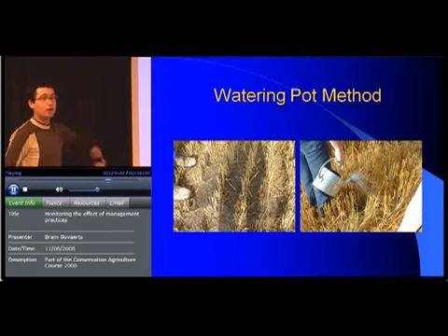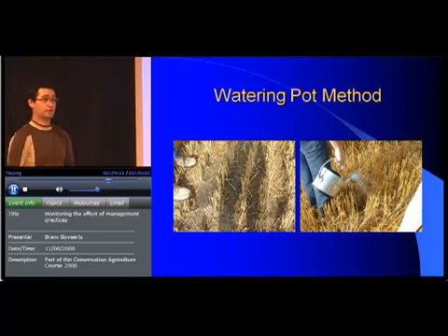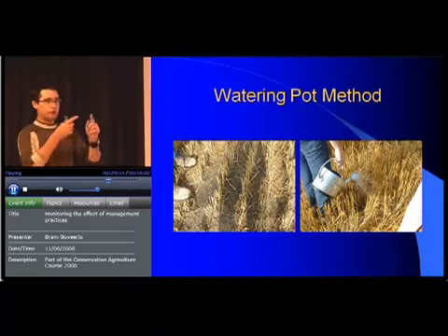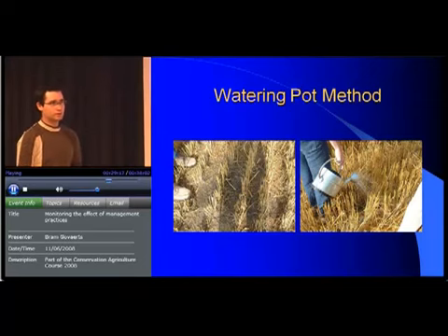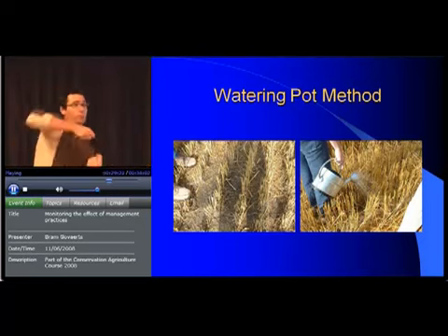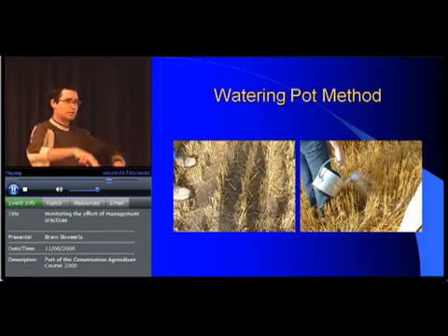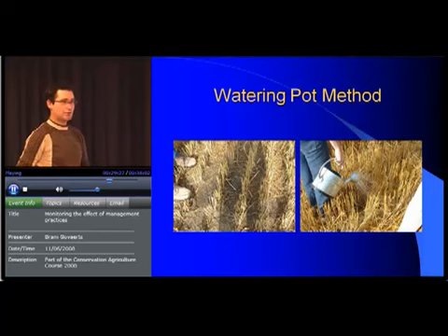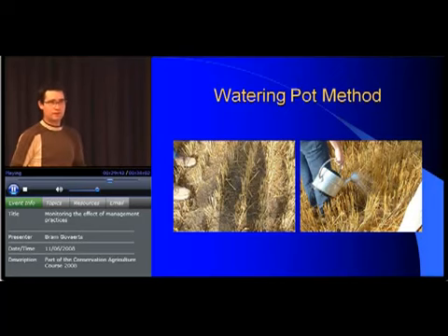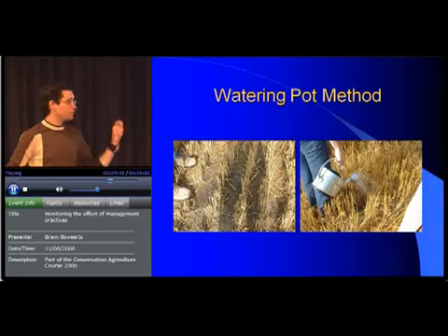Right? Other thing we do is one ring infiltration. And if you measure then moisture, etc., you can calculate from that saturation infiltration. There are other methodologies. You can dig a hole, pour water into it, and see how quick the water is disappearing in the hole, right? So there are lots of methodologies to measure infiltration. You look them up, you do literature search, right? But what I want to say is, my objective was to come up with easy and quick tools that tell you something about rain-fed agriculture. So this one we used in Ethiopia, and it gave good results.